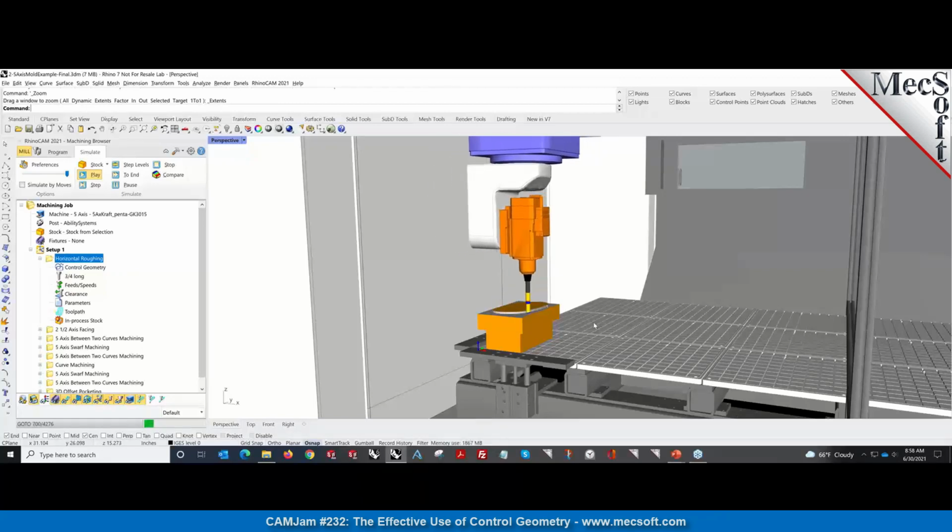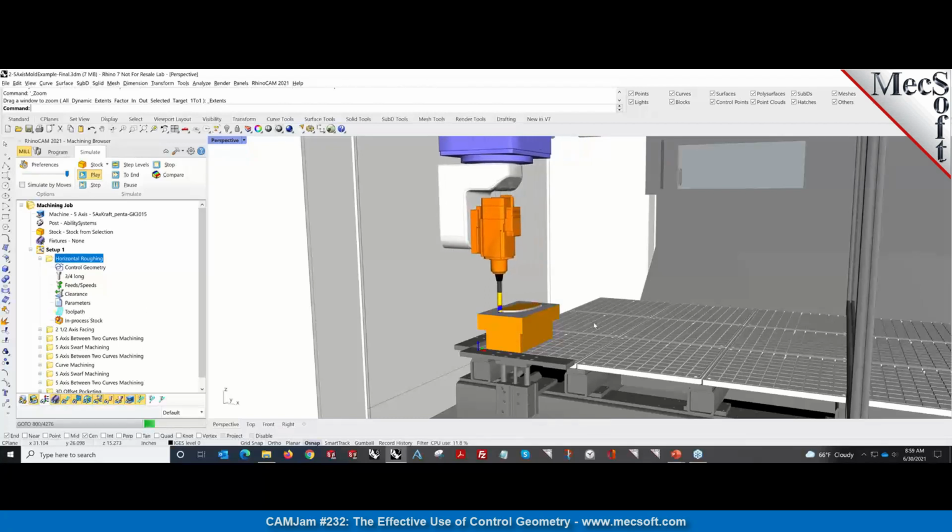Right now, one of the limitations of this machine tool simulation is that it does not do gouge checking. So if your head is hitting another part or another portion of the machine, we do not detect it. This is not a complete machine tool simulation product. This is more of a visual aid for you, so you can see if there are any collisions, purely visually.